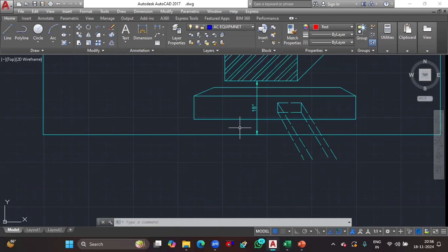That's how we got the main duct height has to be 14 inches. And around this 14 inches, the collar duct height is 10 inches. That means once again, among this 14, 2 inches top side and 2 inches bottom side, isn't it? That's how you got this 10 inches collar duct height, isn't it?